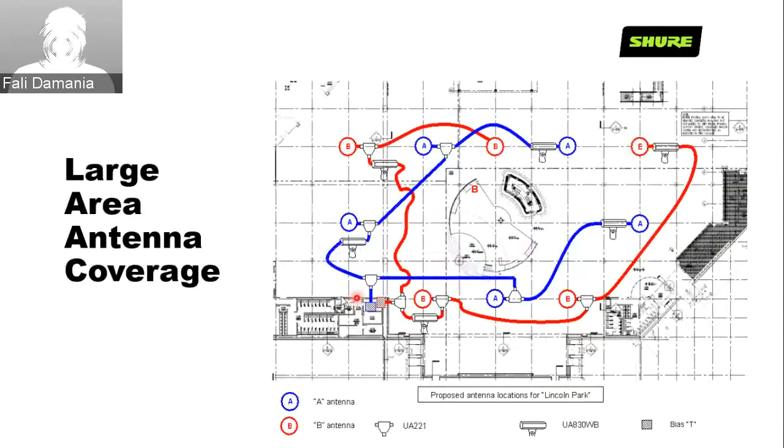This is now a very typical large setup. I think this is taken from a casino. As you can see, the paths, this is how you would typically design it. Once you have an AutoCAD drawing or something, you would plot it to scale on the drawing itself. So you have the entire path for antenna A, where you'll have your combiners or distributors, where you'll have your inline amplifiers, etc., all the way up to the antenna. Similarly here, all the way up to the antenna.